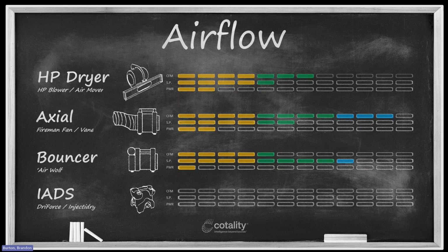It's got a little lower CFM. It's only generating about 1,000, in reality about 600, 700 CFM, but it produces that moderate CFM at a really high static pressure. We get a static pressure here of about 7 inches. Now, this will be the first time I'm going to give you a bearing for what static pressure means. Think about what this blower is designed to do for a second.